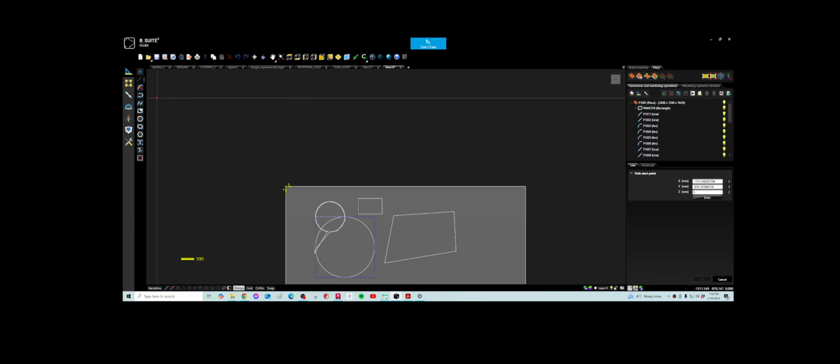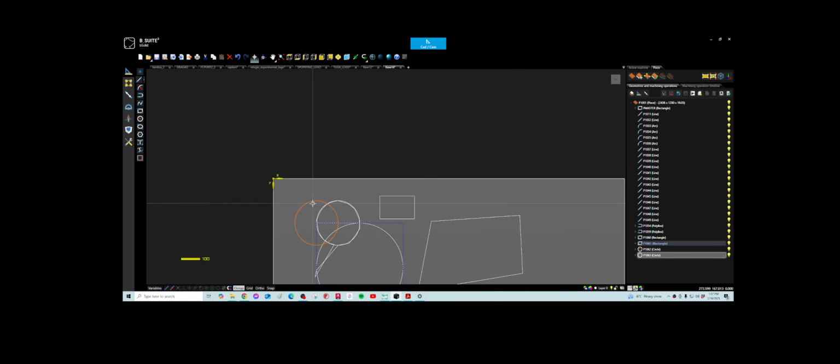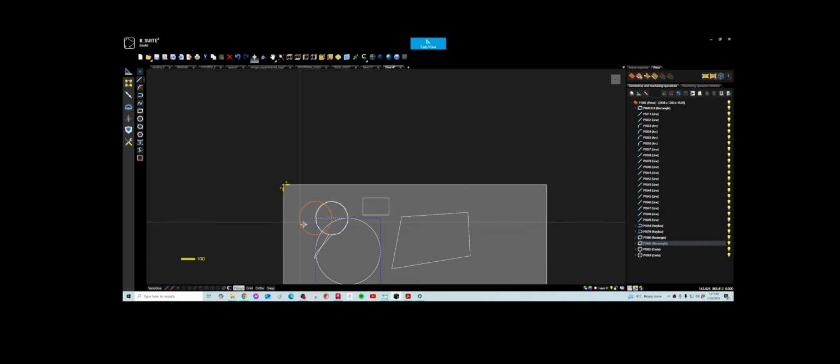So let's go back again to the circle. There's the initial point for the center. Let's make it 300, 300. I don't know why, but I like these numbers. 300, press enter, there it is, and then the radius. Let's put also 300 radius. I have to go there to show where it is, and then here, and put it 300. Okay, so that said, there are these ways to do it. You can find the center, or you can select the corner, and you should be okay.